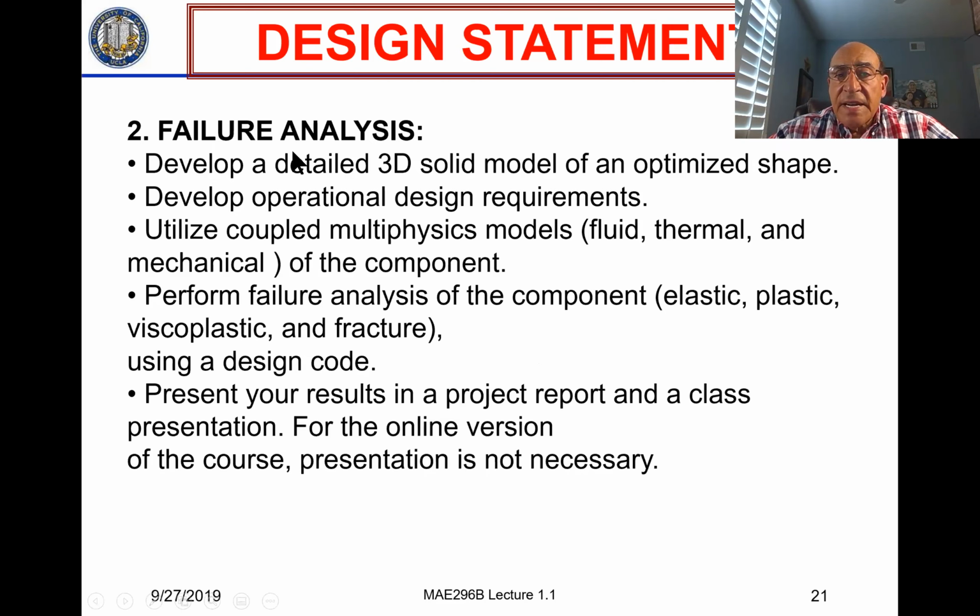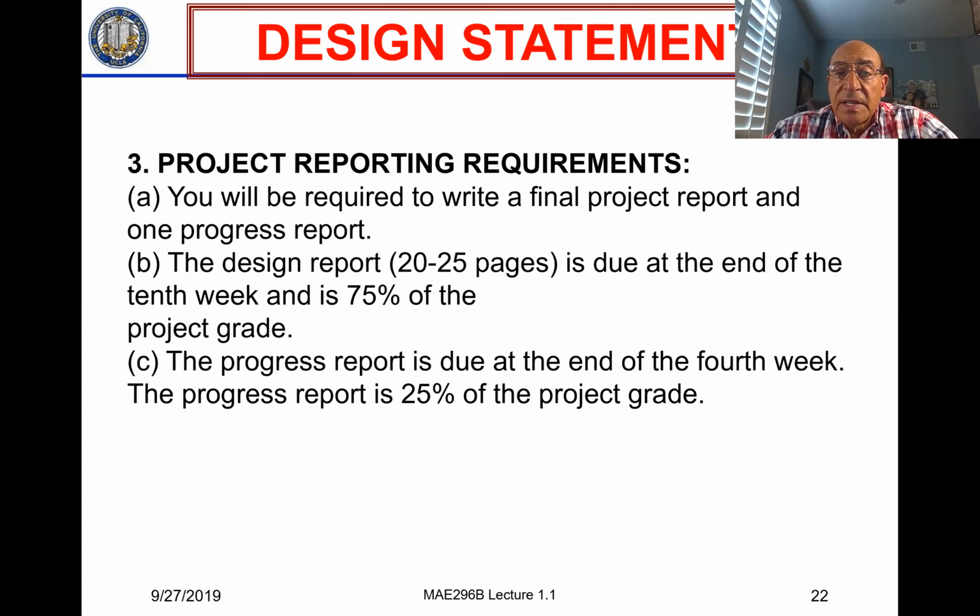So the next step will be failure analysis once we have done the multi-physics simulations, where we use codes that are developed by the American Society of Mechanical Engineers to determine whether the component will fail or not, and also to give us a lifetime for the component based on creep and fatigue type deformation.